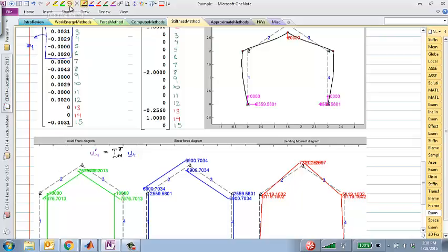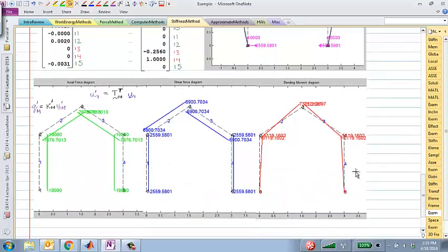Now take that local degrees of freedom and compute local forces and moments: Qm prime equal to the local element stiffness matrix Km prime times the local degrees of freedom. Once you have the local coordinates, then plotting these axial force, shear force and bending moment diagrams goes exactly the same way that we did for the beam problems, right?